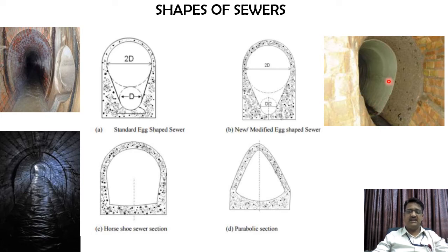And here you can see three types of materials also. First one is brick, which is exposed. As I was saying earlier, if water or sewage gets in contact, these bricks can easily absorb it, and in turn it can exfiltrate to the outer side. Along with that, you can see a concrete finishing, so here the resistance will be more. And here there is some kind of lining available, which is quite smooth. The hydraulic efficiency of this will be higher. Here the hydraulic efficiency will be lower, the reason being it is quite abrasive to the touch or movement of liquid.